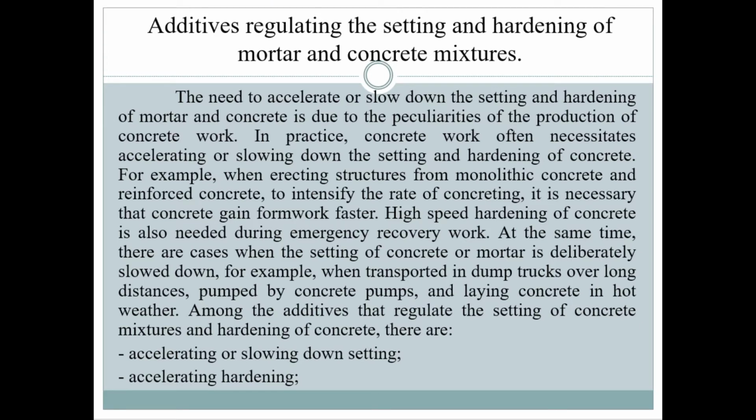In practice, concrete work often necessitates accelerating or slowing down the setting and hardening of concrete. For example, when erecting structures from monolithic concrete and reinforced concrete, to intensify the rate of concreting, it is necessary that concrete gain formwork strength faster. High-speed hardening of concrete is also needed during emergency recovery work.